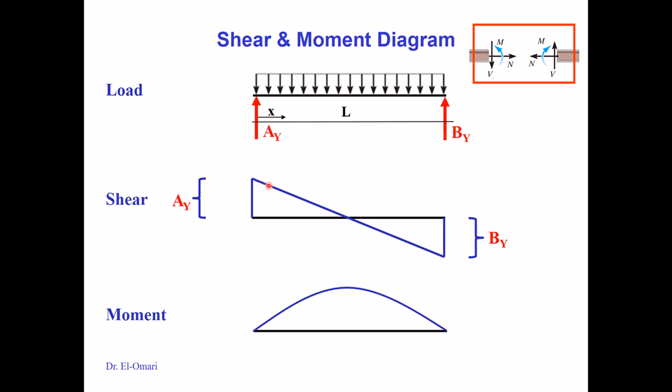This positive decreasing means that the slope of that moment is decreasing, so it goes from big to zero. That's why it goes up, in a positive direction. So these are some of the notes that were summarized. Again, this is the note where the shear is equal to zero, and it will give you a maximum moment at this point.